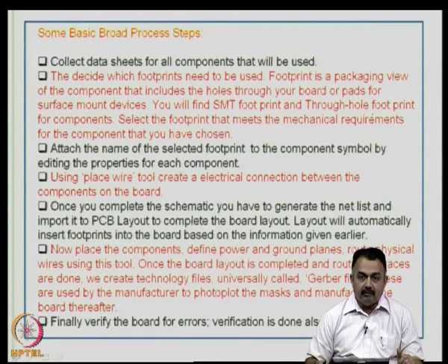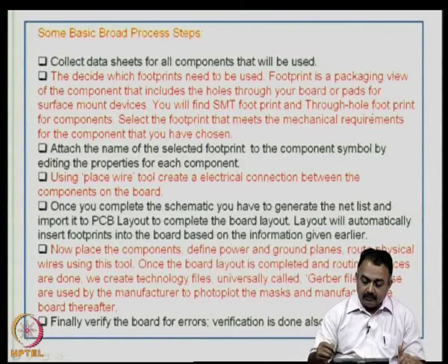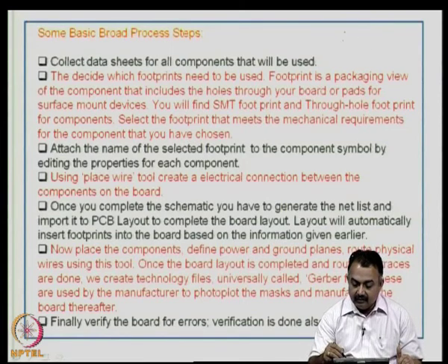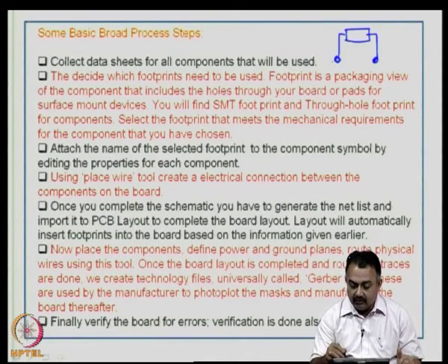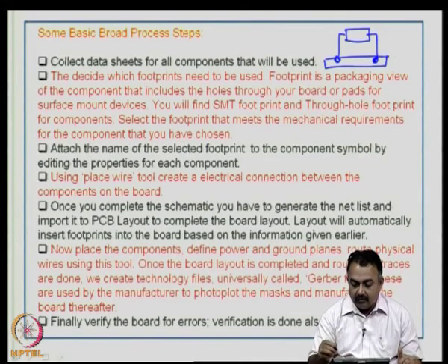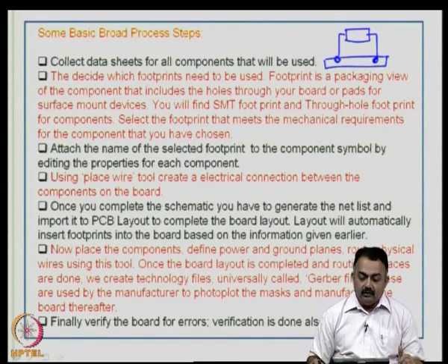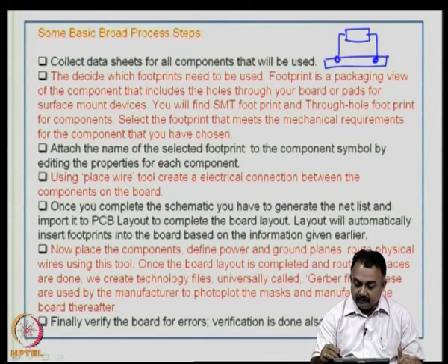Footprint is therefore a packaging view of the component that includes the holes through your board or pads for surface mount devices. So, if you have a resistor, for example, a through hole resistor, then you should have the information about the hole size. So, that goes onto your board. Okay. So, this is known. So, this is a footprint.